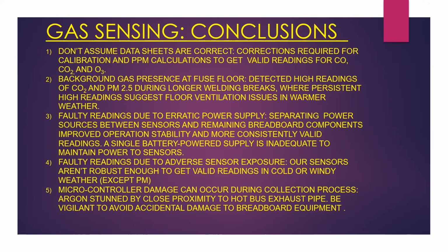Another conclusion is that faulty readings were due to erratic power supply, as we already mentioned, but we discovered that separating power sources between the sensors and the remaining breadboard components definitely improved the operational stability and gave us more consistently valid readings. Our initial configuration of a single battery-powered supply was not adequate to maintain proper power to the sensors, and they would just stop working.